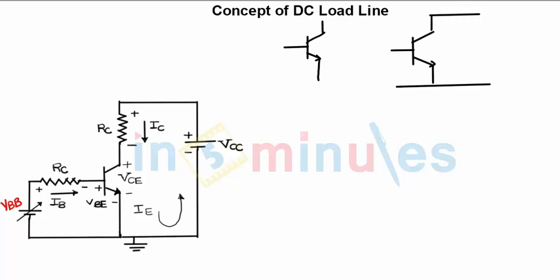Now to just refresh the concepts, to identify this type of transistor. This transistor which is given is NPN or PNP. As I have told you, the arrow marks the P and N direction. So the arrow is always from P to N. So this is P, this is N, and the other side is N. So this is an NPN transistor.